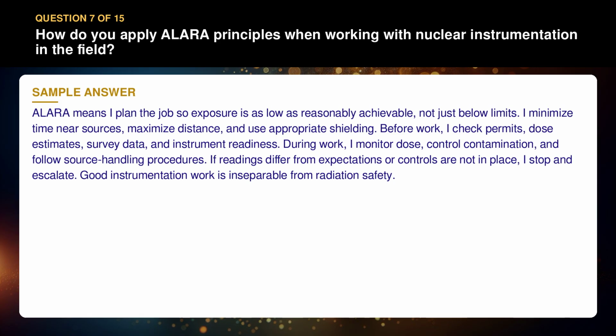Before work, I check permits, dose estimates, survey data, and instrument readiness. During work, I monitor dose, control contamination, and follow source handling procedures. If readings differ from expectations or controls are not in place, I stop and escalate. Good instrumentation work is inseparable from radiation safety.